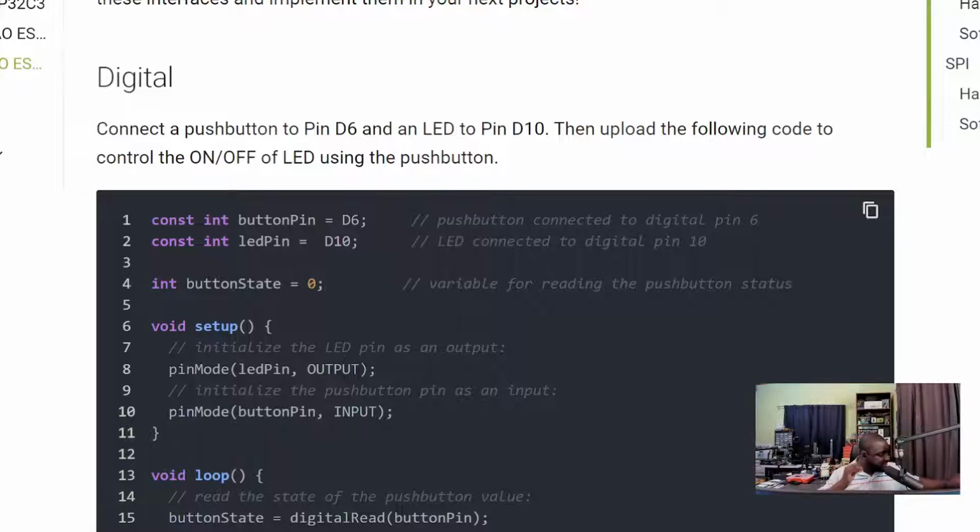So let me share something with you real quick. Let's see this. That was one of the reasons, when we were trying to connect our temperature and humidity sensor, it wasn't functioning the same, because we had to tell it that we're using the digital pin, because the pins can multiplex.